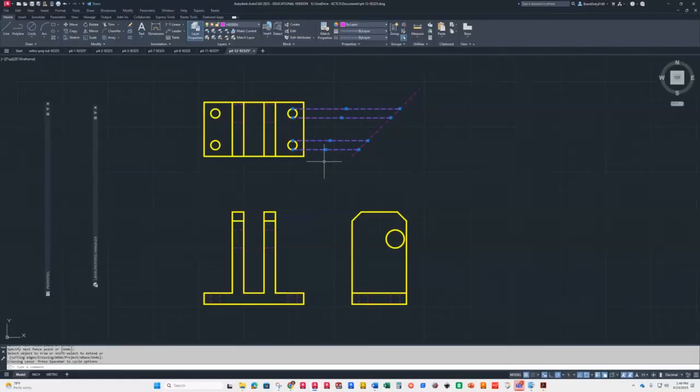Yes, there is. Okay. So I'm missing my chamfer lines for up here, which is one of the lines that's missing in your book. So let's change it back to object line, go to line, and then draw this up and over.